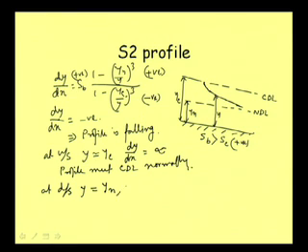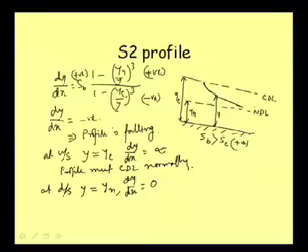So, this indicates that dy/dx is equal to 0, and mathematically saying dy/dx equal to 0 physically means that the profile will meet the NDL asymptotically. Well, so what will happen here, this line will be meeting this normal depth line asymptotically.